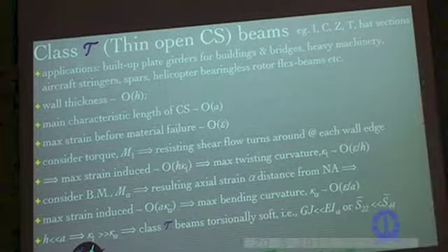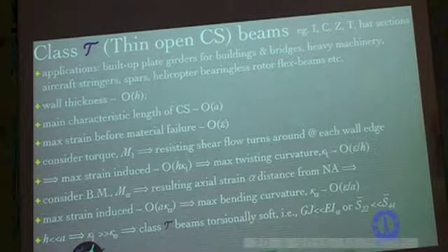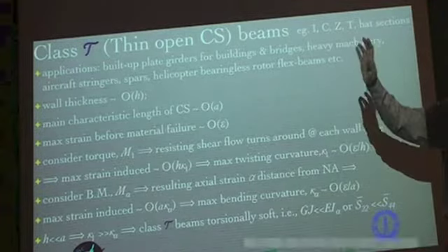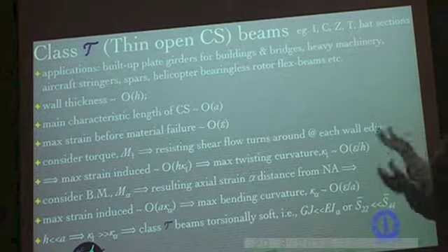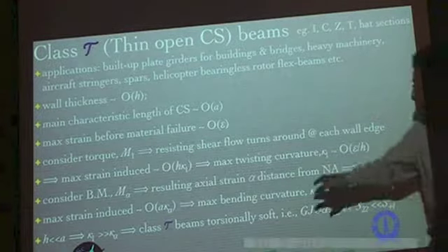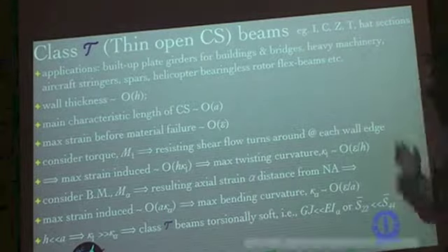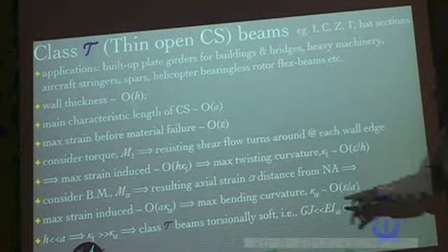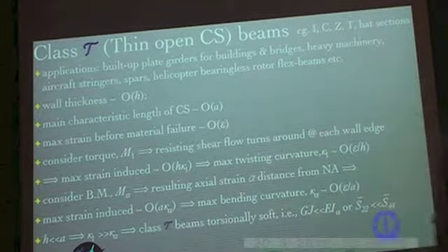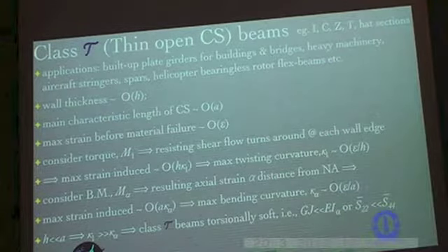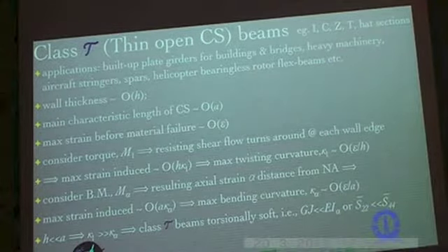That is, your effective GJ, even if it's a composite material, you can talk about that particular stiffness which is associated with kappa 1. So basically in terms of energy contribution, it would be that thing which multiplies a half into kappa 1 squared, the major contribution to the energy. So that's your GJ, and that is much less than either of the EI alphas, that is EI2 or EI3.